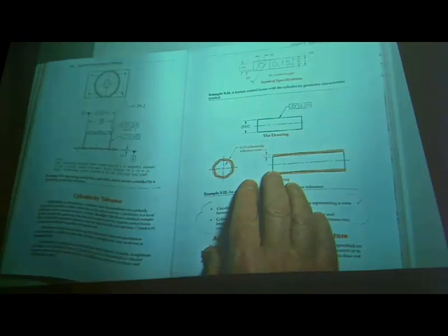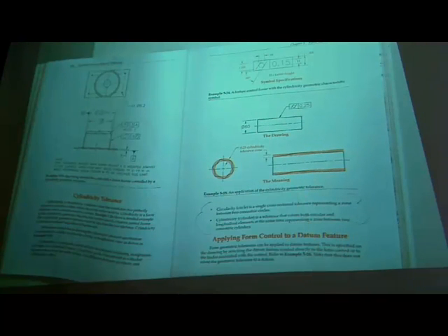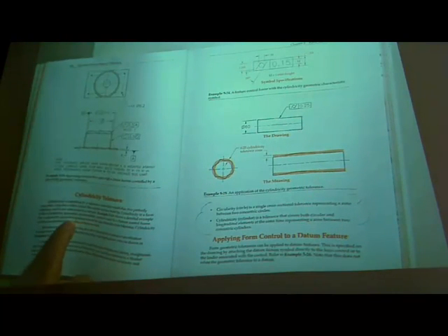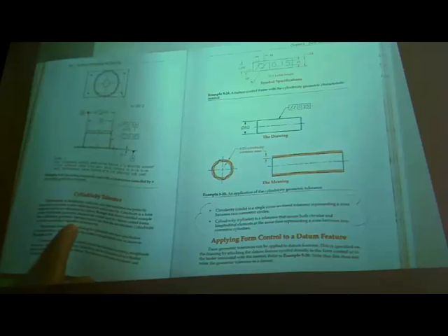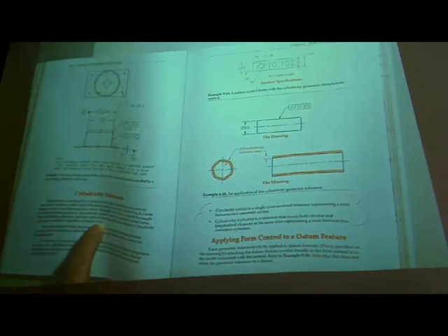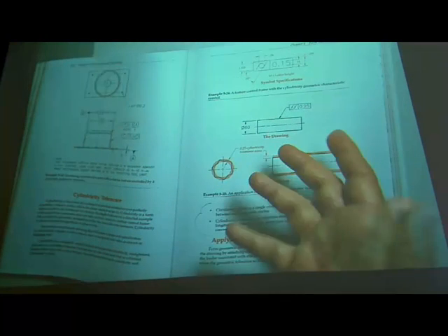We don't really get into all the ins and outs of it very much. It's kind of the same thing as circularity. It must be less than size tolerance. It's always considered regardless of feature size. So we didn't run a chart and beat that dead horse again in here. You know what that means now, and you can look at the example of circularity. It's a concept you should have by now.